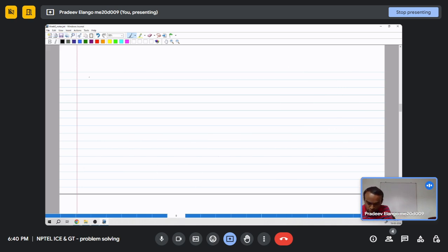So next is Q in. Q in is mCp, sorry, in specific terms we write only Cp into T3 minus T2, and Cp is known as 1.005, and T3 is 1000 Kelvin given in the problem, and T2 is what we just found, that is 628.7 Kelvin. Can you calculate Q in?